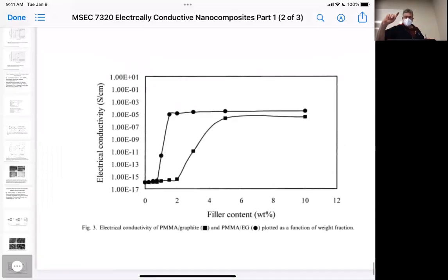Okay. And I think we should use the expanded one because there is no difference between the conductivity that much. Well, it depends on your cost, right? If you want to do a loading of 6% versus 1% to get the same conductivity, is there a cost benefit there? And plus, what's your use? So yeah, I think that if this process is not too expensive to make the expanded graphite, if they just infuse it with like a hydrocarbon and then hit it with steam, which is what they do with mica, it's water and steam. So if it's a scalable process, yeah, expanded graphite is definitely better. And it's probably cheaper than a lot of the others, because you're starting with natural graphite. You don't have to make it by seed.